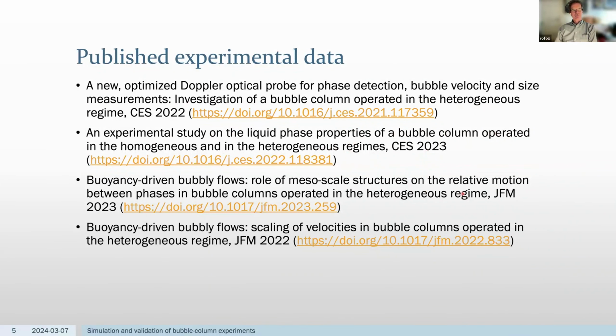And then the paper that is interesting for our case is conditional statistics of what's known as mesoscale structures. And so what you see in the heterogeneous regime is a segregation according to volume fractions. So you get clustering of bubbles that are moving up. They do not coalesce in this case, but they simply cluster together and move up faster than zones that have void fractions.